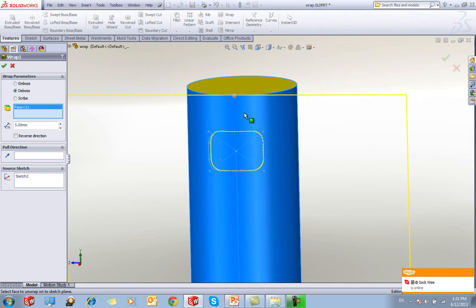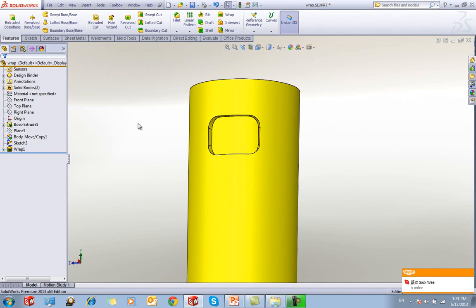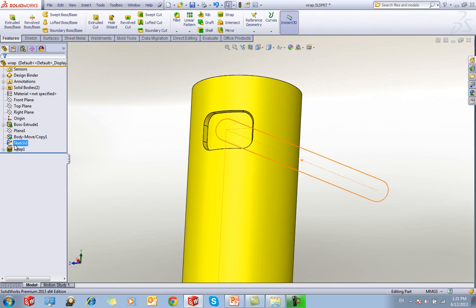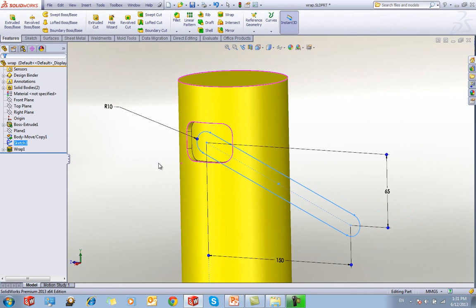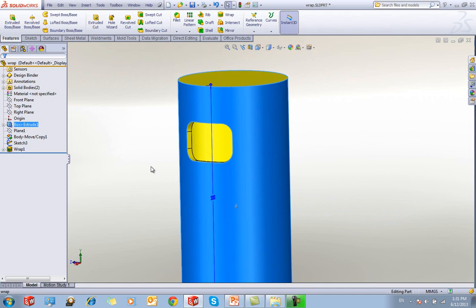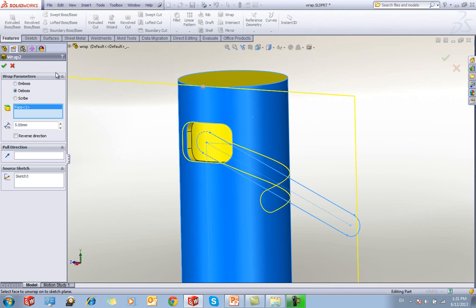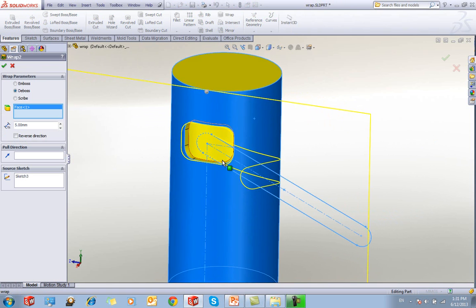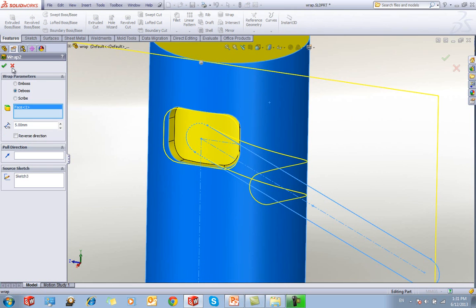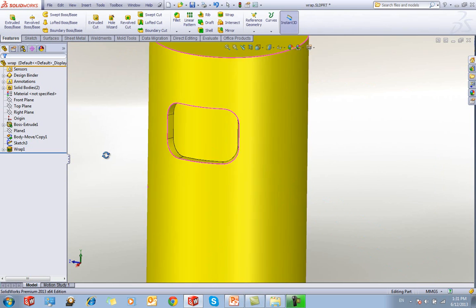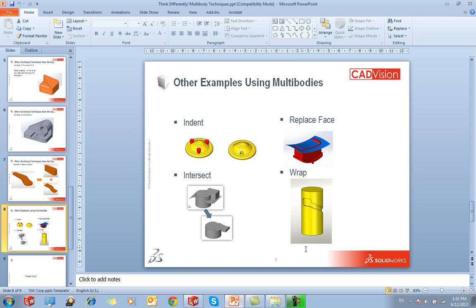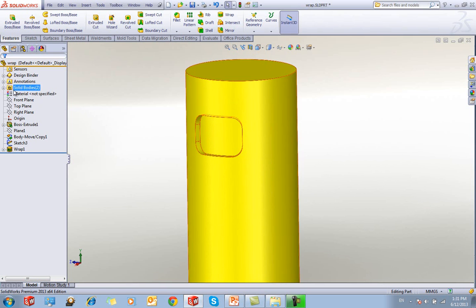Okay, I just select the face and the depth that I want to cut, then I get this pocket. Right now, let's say I want to make a slot, same thing, also web on this face. By right I should click here, everything seems okay, hit okay, but there's an error because of intersection. The face intersects, so it will not let us pass. So what if I insist I need to get this kind of feature, this kind of shape? We can ask for help from Multibody.